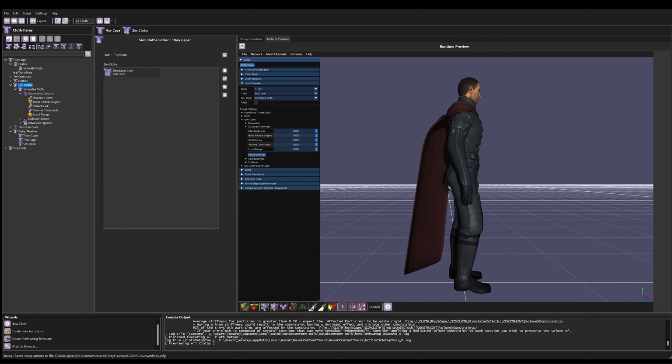Go to the Constraint Stiffness settings. Each constraint field in the preview tool shows the strength of that constraint's effectiveness in the runtime preview on a scale of 0 to 1. 1 means we're seeing the constraint's full effect. 0 means the constraint is turned off. We'll reduce the stiffness of each constraint to 0, one at a time until we find the problem.